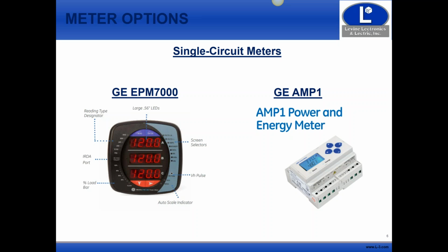The other way that we can do this from a whole panel standpoint is the switchboard, and GE in particular has some breakers in their main switchboard that you have the option of doing metering on. They're intelligent breakers, and if you add the metering option, then we can get current and voltage and power out of those. So we connect those via RS-485 back to our system in order to pull that data. So those are some different options.